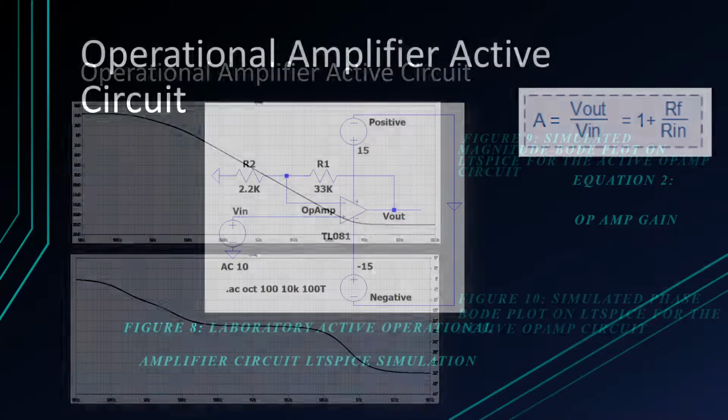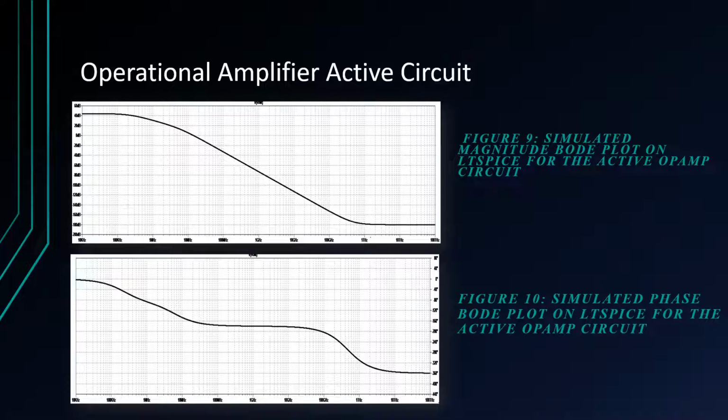Alright, so up next, here I only plotted this on LTSpice, since now I know that's the best way to go about these frequency measurements. And as we can see, it starts from 44 dB and it goes all the way down to negative 180 dB. For the phase, it starts at 0 degrees and it goes down to negative 360 degrees.